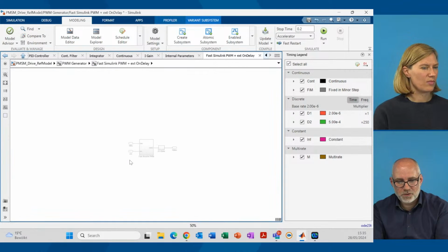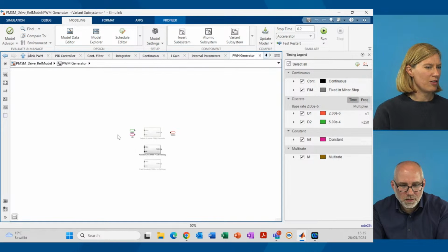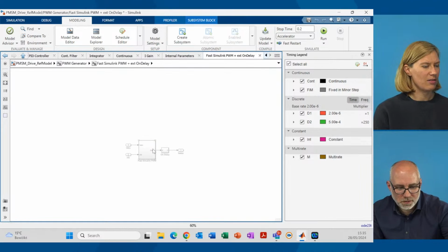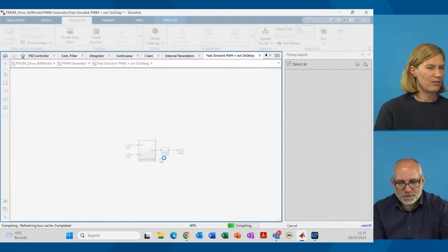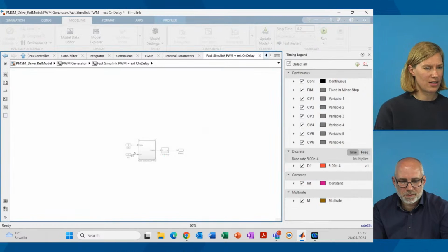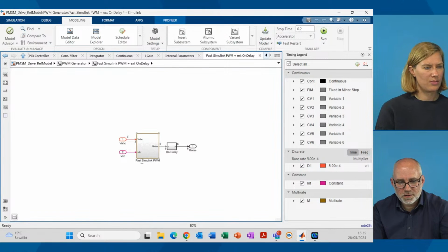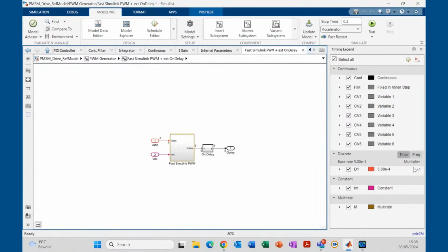And let's also have a look at this log here. So was it grayed out? I think once you press Control E, Control T, we do a model update again, so it applies the change. Yeah, it's easier to see. What you see here is we are coming in here with the red signal, and be careful now. We have lost one discrete sample time.